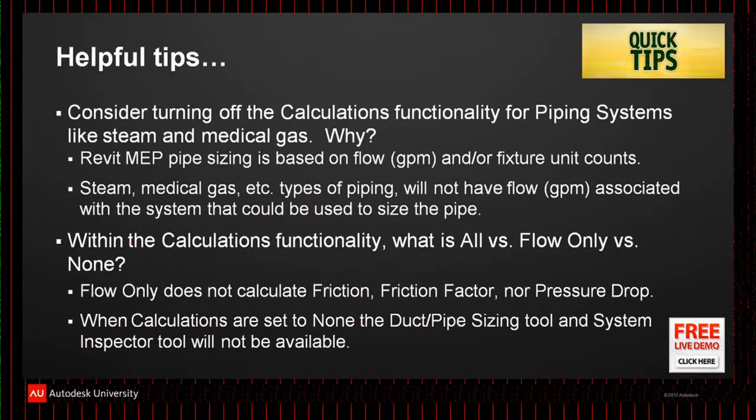Can you actually use the tools inside of Revit to size a steam system or a medical air system? No, because it's not based on GPM or fixture unit count. If it's not based on GPM or fixture unit count, then shut the calculation off. Revit won't even consider that in the calculation portion. You guys will save yourself a lot of time and a lot of headache as your models grow. So we'll talk about how to shut those calculations off.